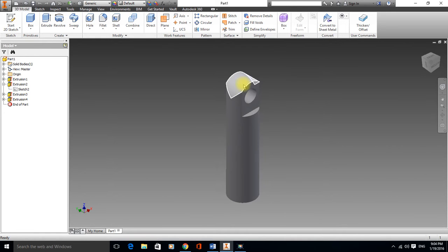You've got a basic 12mm bar. We could hold it vertically in a milling machine, and we could put these faces on by using an end mill and going down each side. And that's the first way I'm going to do it.